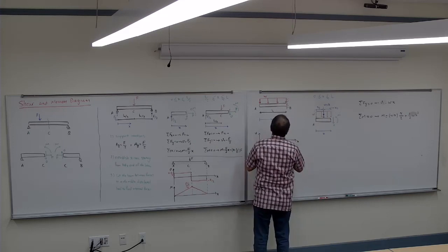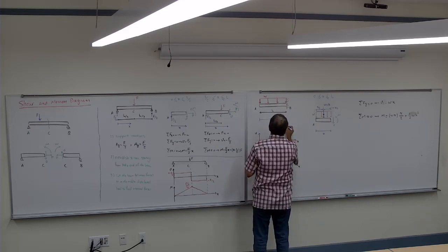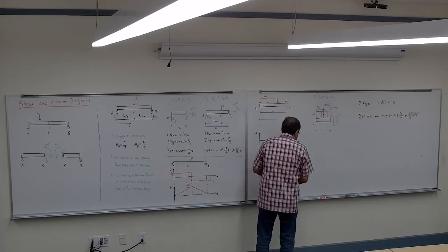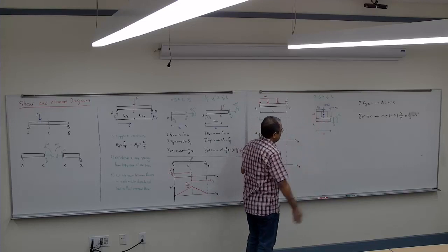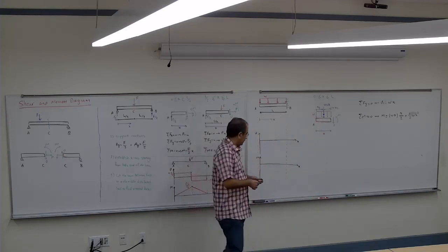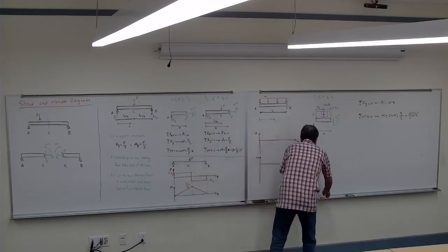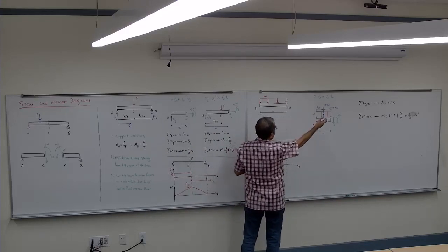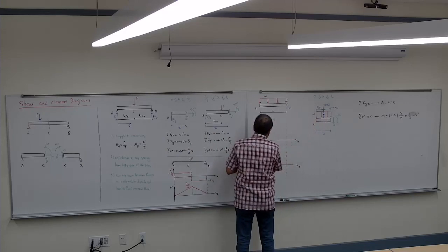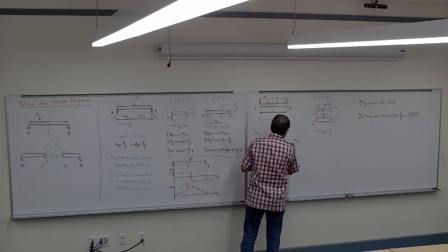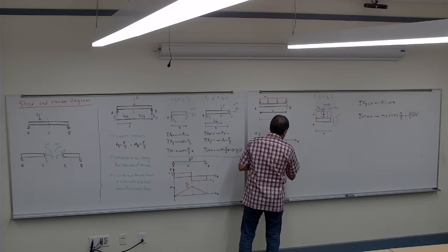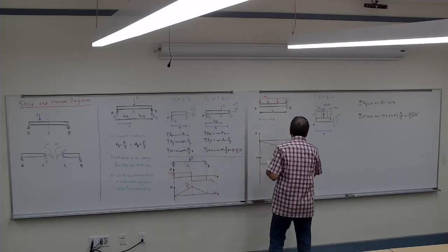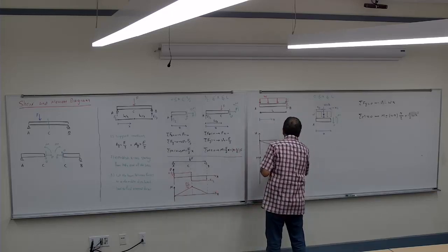And then I have the end of the beam, so I just mark that point. So if I draw the V, it is negative Wx, so you get the V starting from the 0, and when it's L, it's going to be negative WL, so it's going down like that. So at that point, it's negative WL.